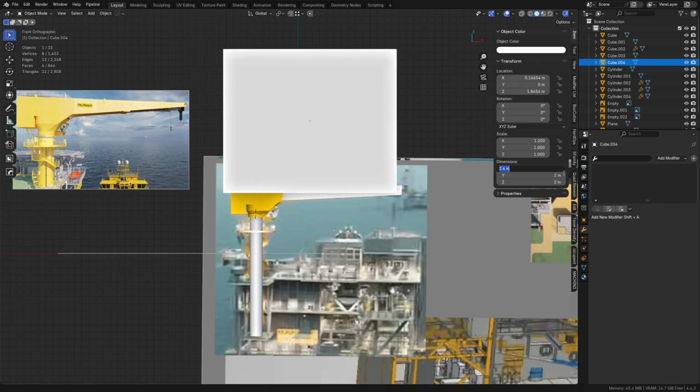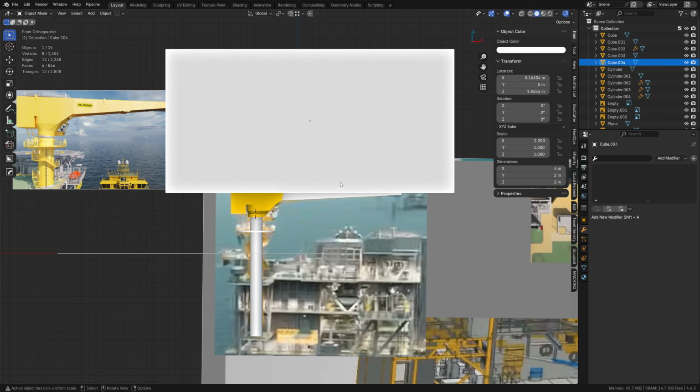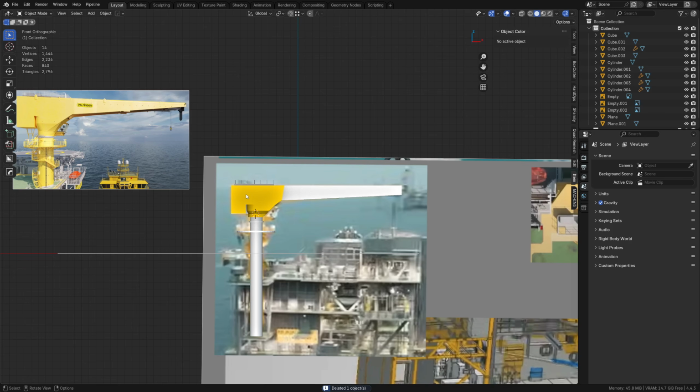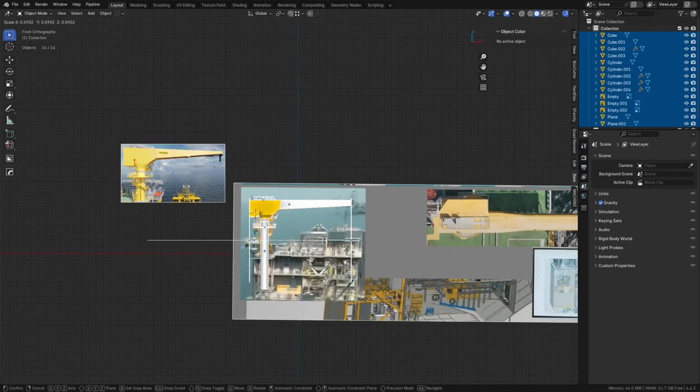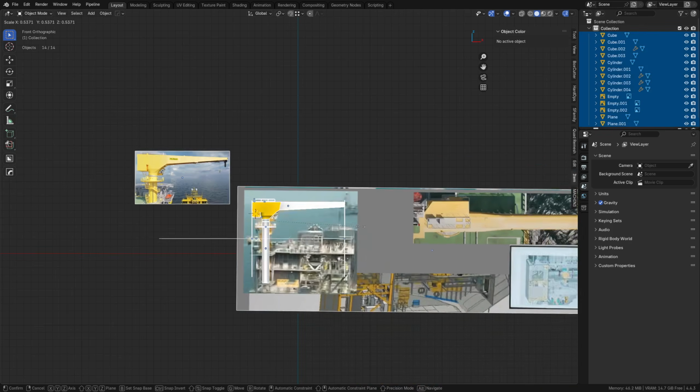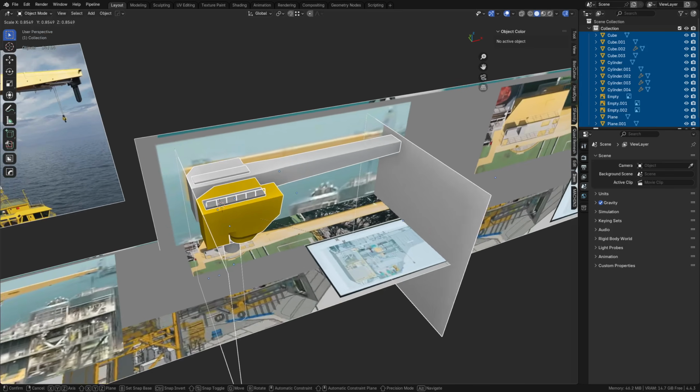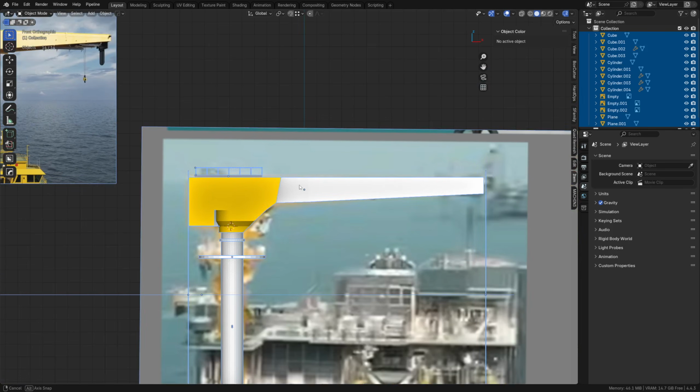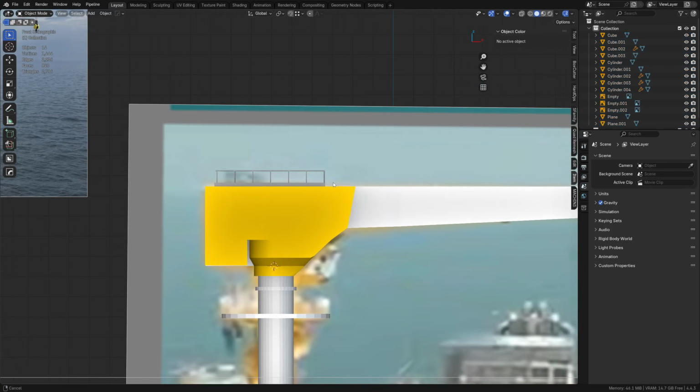I'm just going to say 2 meters for now, but you get the idea, like 4 meters maybe. You can type in whatever values you want, 4 meters, 20 meters, centimeters, inches, whatever you got to do. And then you set up a cube like that, and you would scale everything to match that cube after you get the scale right. Sometimes the modifiers go crazy when you scale things, so be careful. Don't go too far with modifiers.